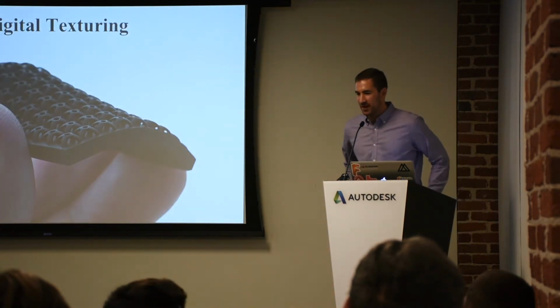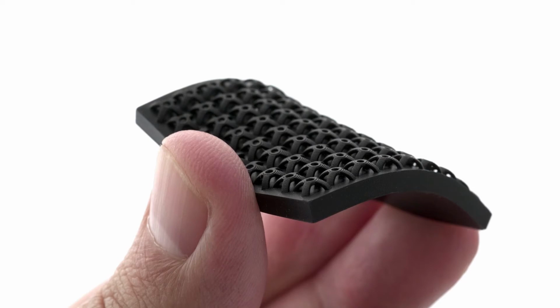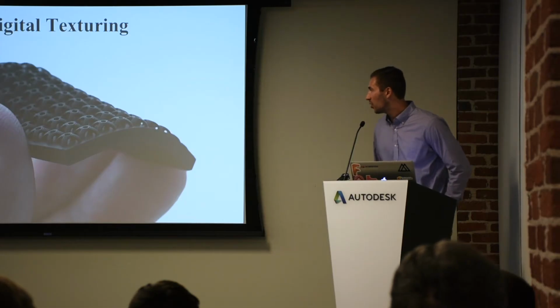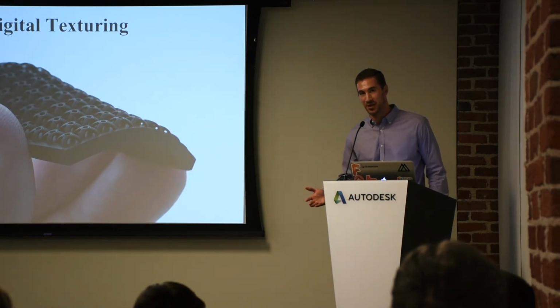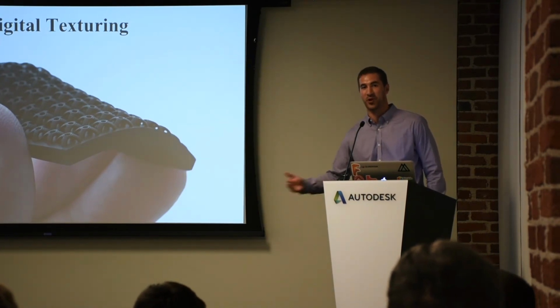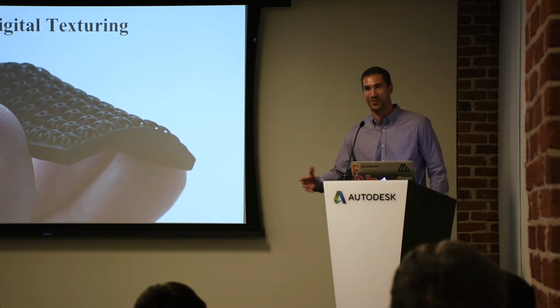One thing we're really investing in, experimenting with different customers, is what we can enable with new digital texturing. You look at almost any product out there today, especially the surfaces inside your car, and they have some sort of texture on them, right? For aesthetic value, sometimes for a tactile experience. It feels good. It doesn't feel or look cheap. That's been done by injection molding for a long time, and it's a pain to do with injection molding. It's the last thing you do before you go into production, so you don't really have it at the prototyping stage. So that's one clear advantage.